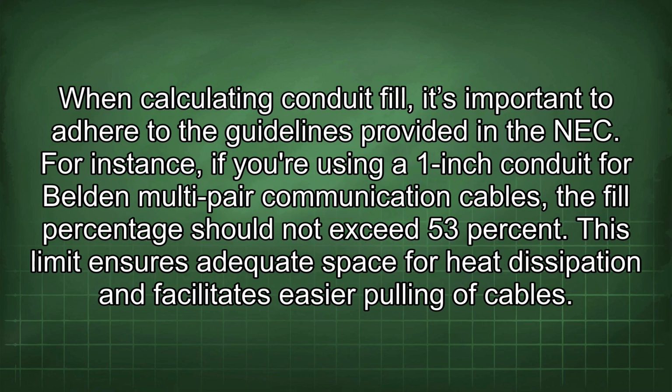When calculating conduit fill, it's important to adhere to the guidelines provided in the NEC. For instance, if you're using a 1-inch conduit for belted multi-pair communication cables, the fill percentage should not exceed 53%. This limit ensures adequate space for heat dissipation and facilitates easier pulling of cables.